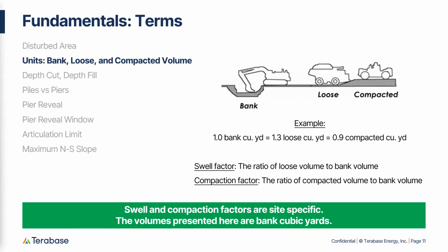Talking about units in terms of volume, I think it's important to understand what units we're talking about. We want to be clear on that. Soil will change volume as it moves around the site. One cubic yard of in situ soil will occupy a little more volume once it is excavated, and a little less volume once it is placed and compacted. The amount by which it swells is called the swell factor, and the amount by which it compacts is called its compaction factor. These factors are very site specific, and they vary based on the soil types.